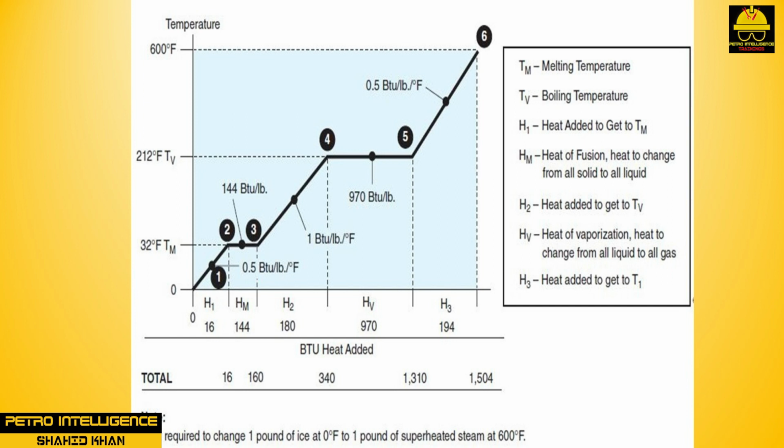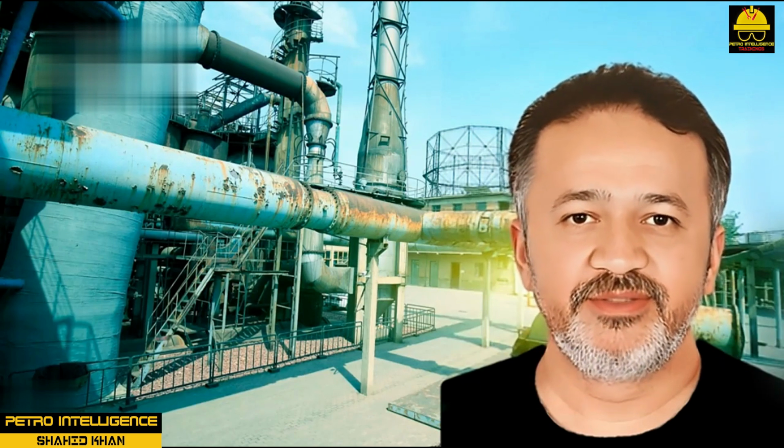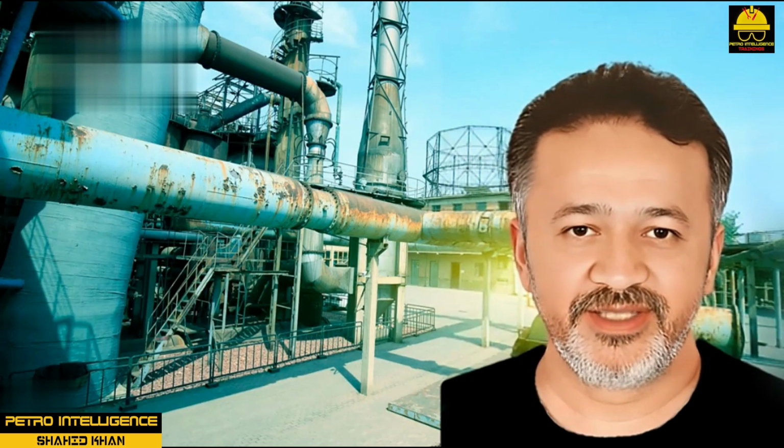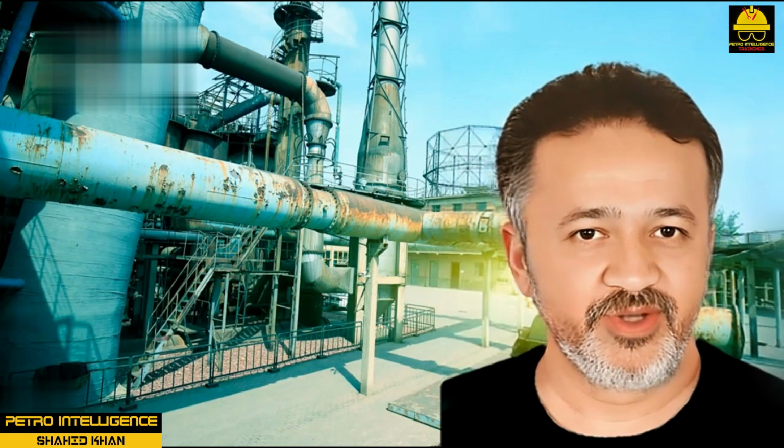Local water reservoirs and storage systems have a wide range of natural water quality, including various amounts of impurities. At higher temperatures, the dissolving nature of water is enhanced, so the amount of dissolved solids may be increased. Water hardness is associated with the presence of calcium and magnesium compounds. Salt water varies from fresh water in the salt mineral content of the water. Salt water contains 300 pounds of salt for every 1,000 pounds of water.